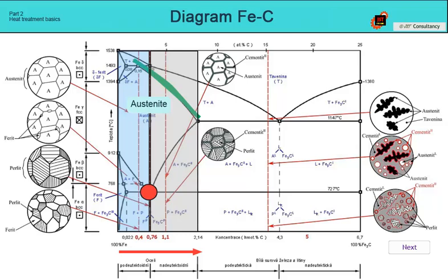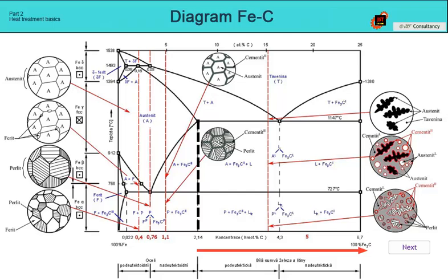There are hypereutectoid steels. The solidification of hypoeutectoid steels passes through the curve with temperature A3, where a ferritic-perlitic structure is precipitated from austenite. The solidification of eutectoid steels passes through the eutectoid point, and in this unique case, the austenite changes to 100% perlite. The solidification of hypereutectoid steels passes through the transformation curve ACM, when the structure changes to a structure of perlite and secondary cementite.